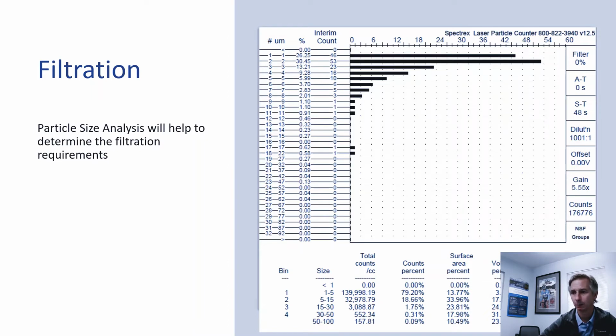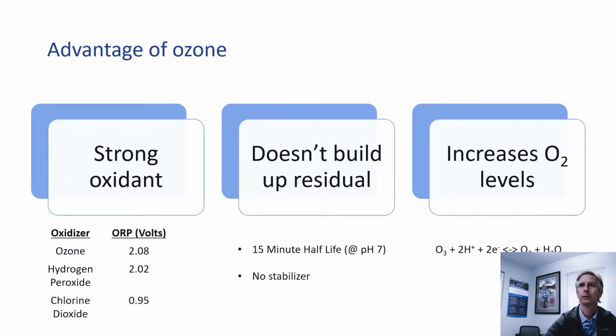greater than 15 micron. Therefore, we would need to establish the right filtration technology to account for both the mass and the particle size, to both avoid fouling of the system and also to have sufficient removal of the plant material so that we can lower the BOD in this irrigation water. So that talks a little bit about the filtration side.